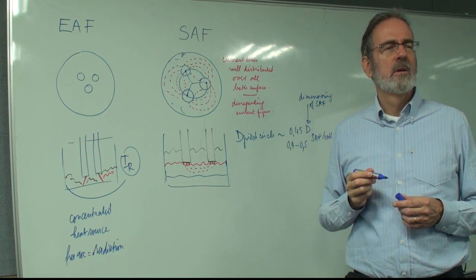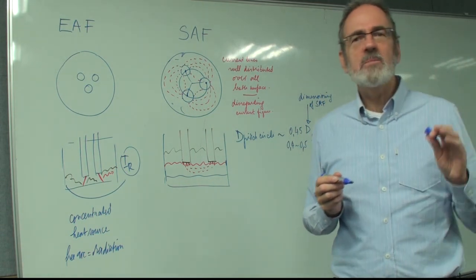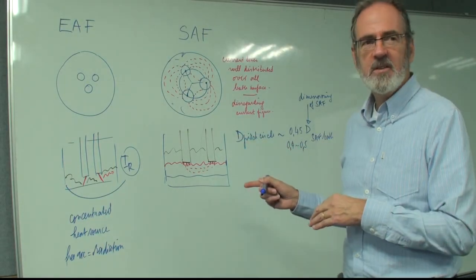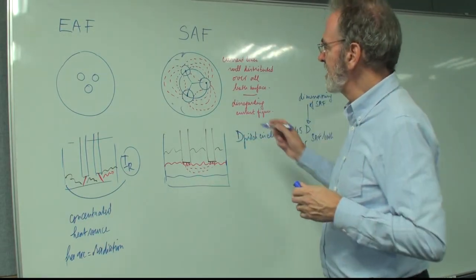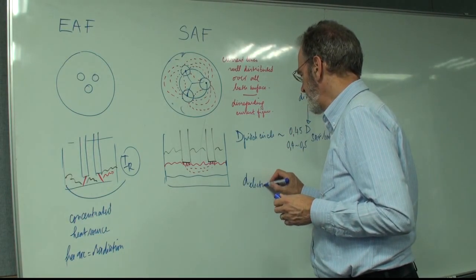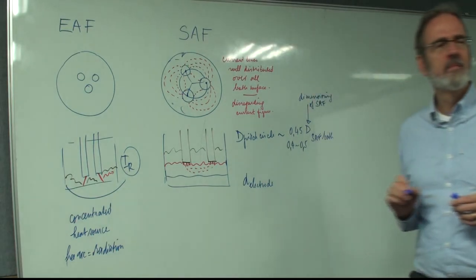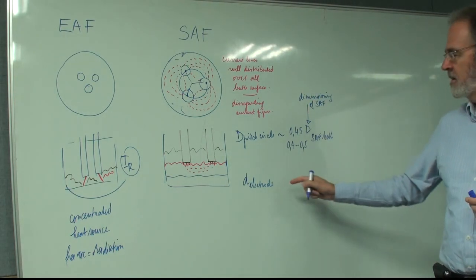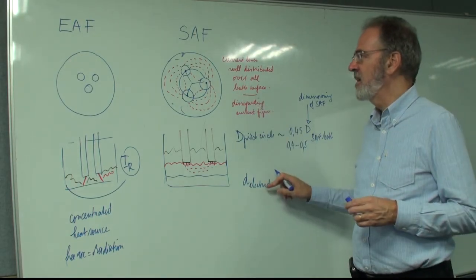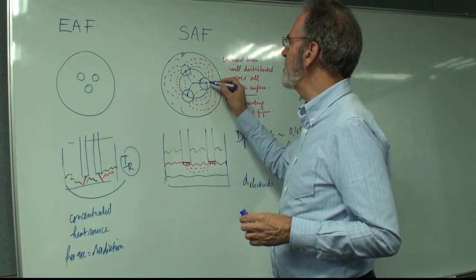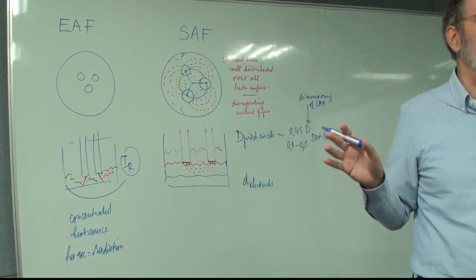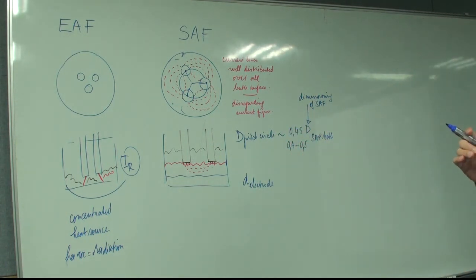I can calculate the distance between electrodes. There you need the diameter of the electrode, and that's the second formula. Diameter of electrode. And is there any recommended distance between electrodes? No. This is the result, because if you know the pitch circle and you know the diameter of electrode, the distance is forced.